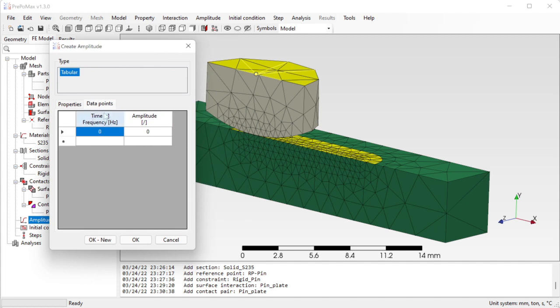In this case, we are dependent on time. For dynamic simulations, there is dependence on the frequency. So in this case, don't confuse the frequency of the assignment with this frequency here. It's not the same. This curve could be any kind of curve. It could be just a bilinear curve that we will do, or it could also be a sine wave or something else. It's not exactly described in the assignment, but because we can enter the sine curve, we would have to compute it in front. I didn't do that. I will just use a very simple bilinear curve.